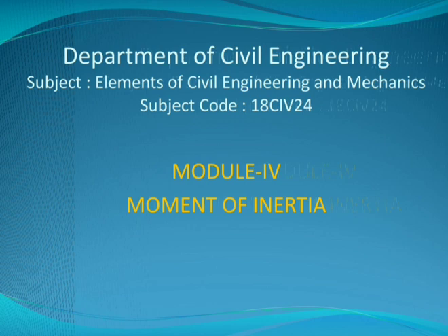In the previous video, we went through the first example, which was an unsymmetrical I section. The section was unsymmetrical about the horizontal axis, but symmetrical about the vertical axis. Hence, in that example, we needed to locate the y bar coordinate of the centroid and find the moment of inertia about the reference axis I11, then obtain the moment of inertia about the horizontal centroidal axis Ix.